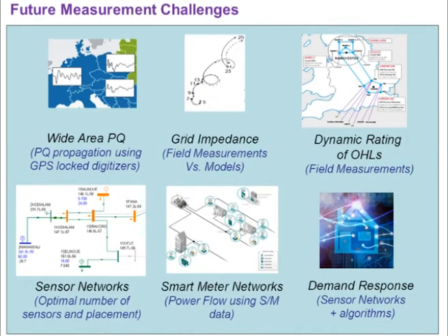That's a question of measuring how the impedance changes with frequency and also with season, such that people who are designing filters and people who are running models of networks can get some better information such that they can do better design. This leads to another thing that you can do with impedance measurement, perhaps has been mentioned today, dynamic rating of overhead lines. And by looking at the resistance change of the overhead lines, it's possible to perhaps give some estimate of the average temperature change in the overhead line, which could be useful for dynamic rating.